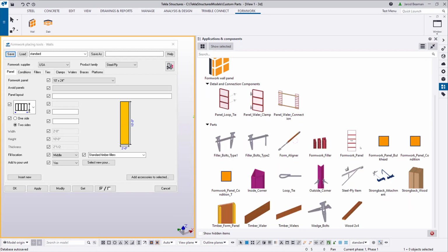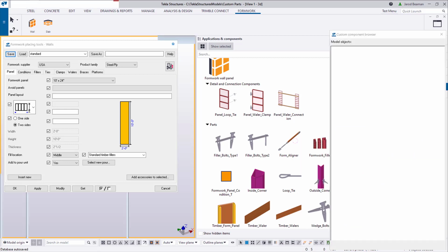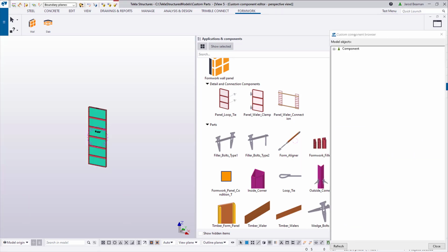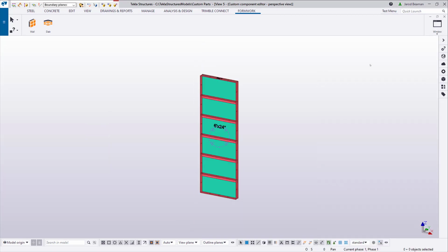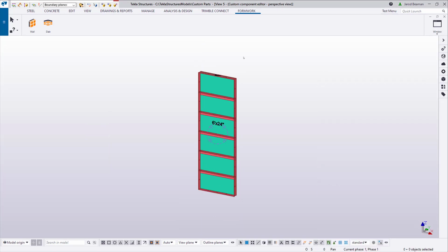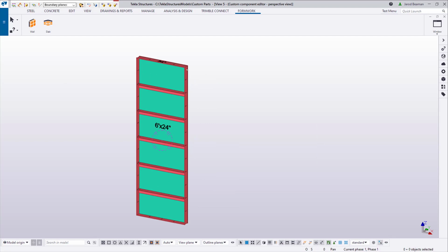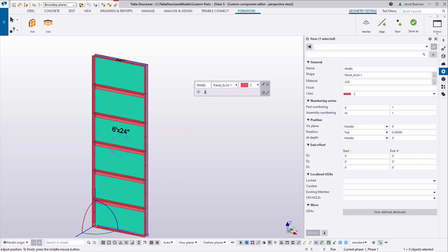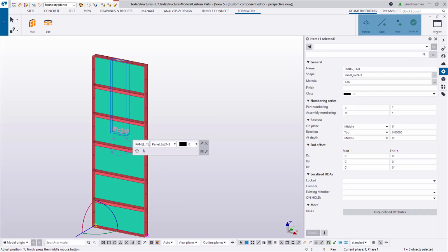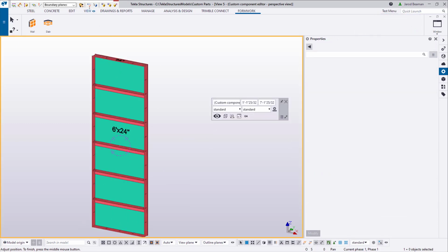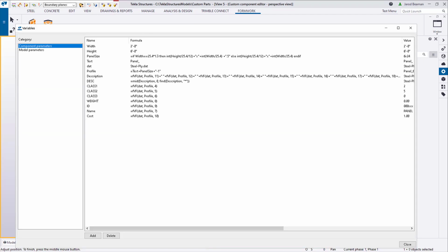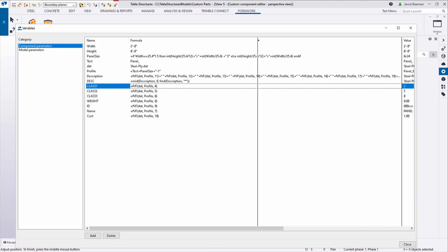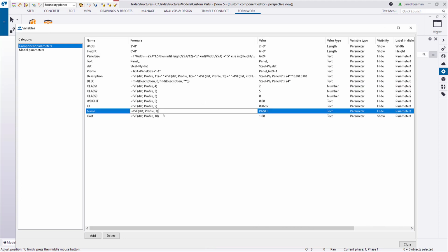Custom parts are required to create along with the configuration files. Inside of those custom parts or components are items and parts. Items are imported if their geometry has been created in external software, or you can create these items in Tekla. In the component, the product data is referenced from an external file, and this can include properties like a product code, weight, description, and are written to user-defined attributes of the items to appear in reports, drawings, and for your use in filters.